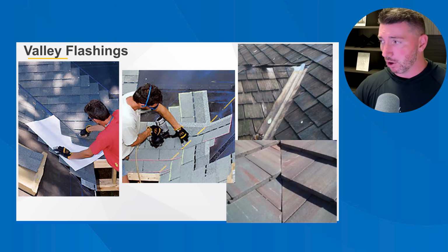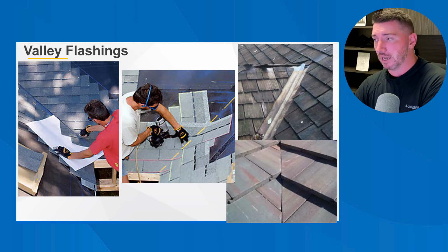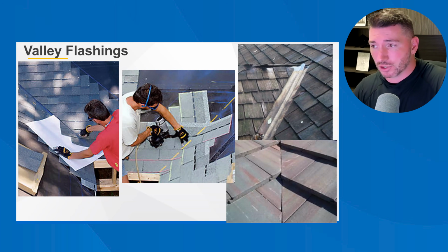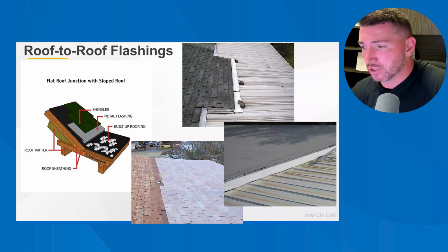You just have to be aware that you'll have to seal the outer edge of that down to it so that no water can penetrate up. Valleys are one of your biggest weak spots, so I would recommend definitely taking pictures of the valleys as you go.